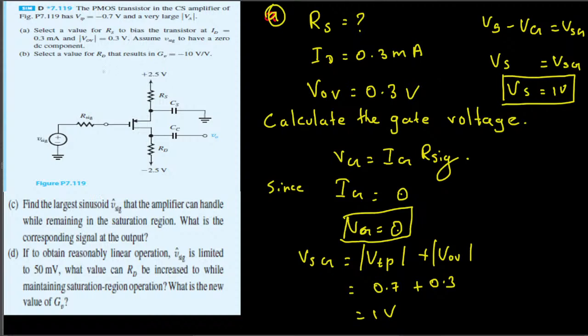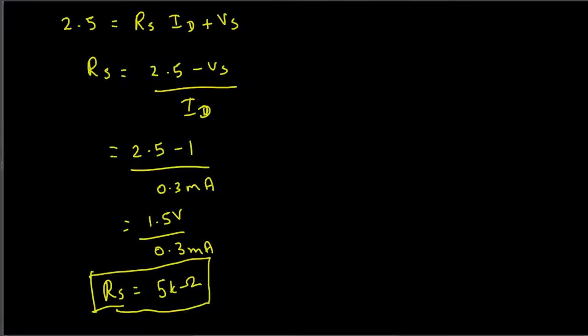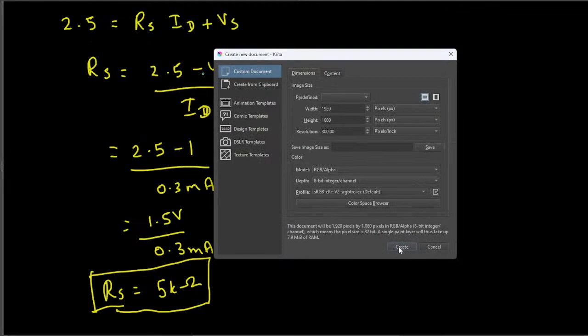Now in order to deal with this one, we have to find out the transconductance, because there's an equation given for Gv. Gv is given by V0 over vsig, and that is also equivalent to minus Gm Rd. This second form is helpful for us because we have Gv available. We can find the Gm, that is the transconductance.